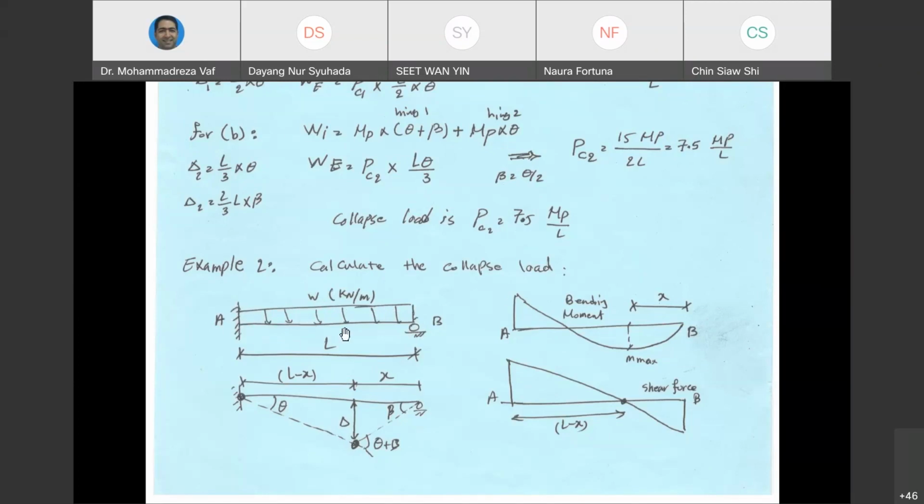But we don't know the exact location of the bending moment for the positive side of this cantilever beam. Similar to what we said for other beams, in order to reach the collapse condition, we need to have 3 hinges. One of the hinges is already there because the support is a roller. We need, therefore, 2 plastic hinges due to the increase in the force that makes the structure collapse.